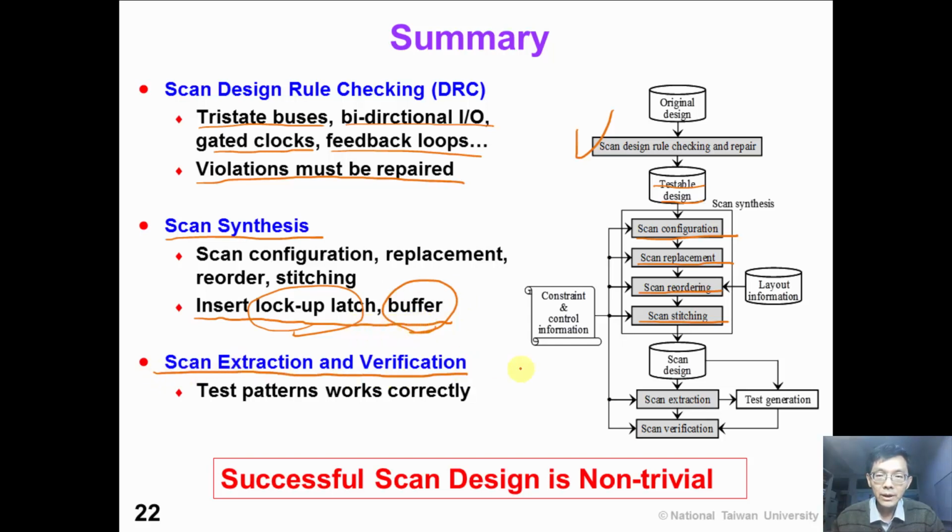Finally, after ATPG patterns have been generated, we also need to verify that the test pattern works correctly in our scan design. In conclusion, you might think that scan design insertion is a simple job, but actually it's not. A successful scan design is actually non-trivial. It requires a lot of work before we can make sure our test can be applied successfully.